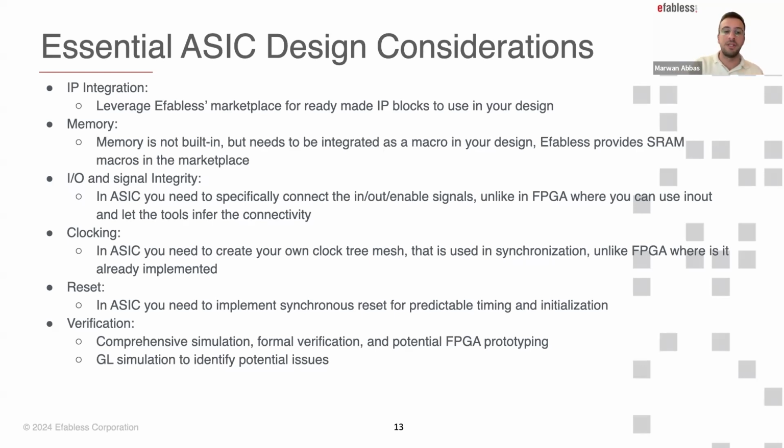And also for resetting, you have to have a synchronous reset in ASIC to ensure that you're timing clean and you have a clean startup sequence, and that helps avoid unpredictability in your chip. And finally, verification. This is a big one because in ASICs, it's permanent, right? So verification is very crucial. And that includes simulation, formal verification, and in some cases, you can even do prototyping using FPGAs.